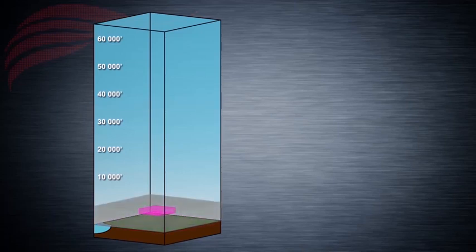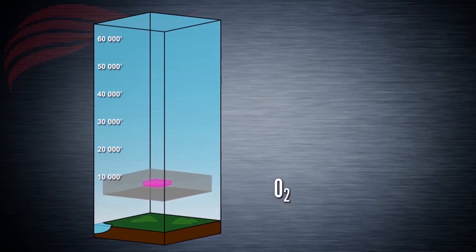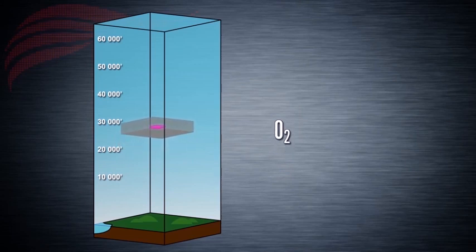For example, the amount of breathable oxygen at sea level is approximately 21% of the total air. If the air pressure at sea level is 1,013.25 hectopascals, the mean pressure exerted by oxygen is 212.8 hectopascals. As altitude increases, air pressure reduces. Therefore, the concentration and pressure of oxygen also reduces to about 30% of sea level value at flight level 300, which is only 63.8 hectopascals.